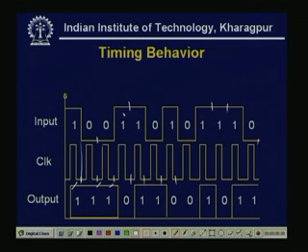Now, a 1 arrives in the input bit, so there are an even number of ones, now there are 2 ones. So, the odd parity checker will generate a 0 output. Similarly, if another 1 comes, then there are 3 ones, so the odd parity generator will give a 1 output, next 0 again 1 output, next 1 and it becomes 1.